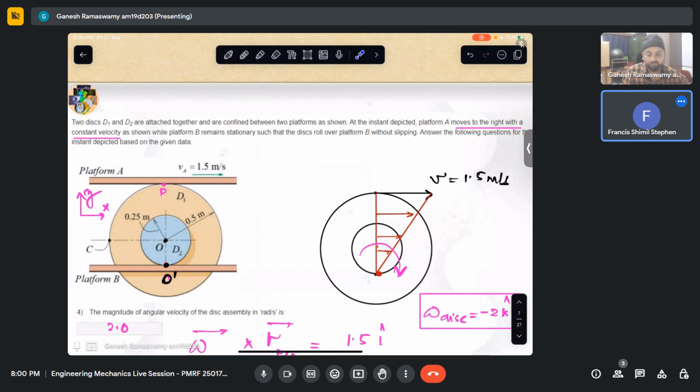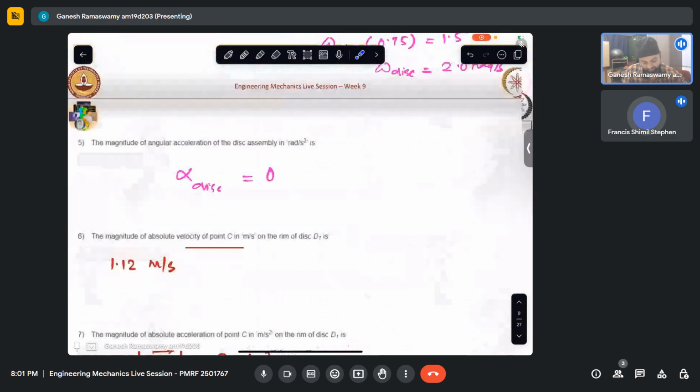As long as there is one rigid body, it can only have a unique alpha and unique omega, no matter where we see it from. Let us say we observe it from a fixed frame and we have evaluated something. Then we go about in a non-inertial frame and evaluate something. That gives us a via media to link it and find the correction factor that we need to make. Because whatever is observed from the fixed frame is correct and it's universal and it can be only one value for one rigid object. I hope that is clear.